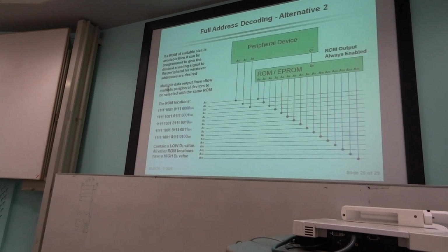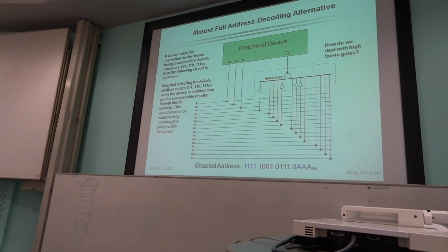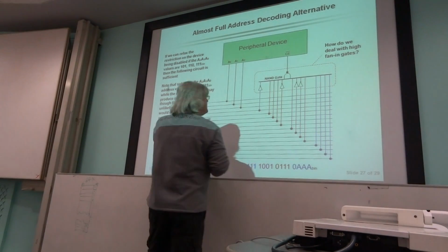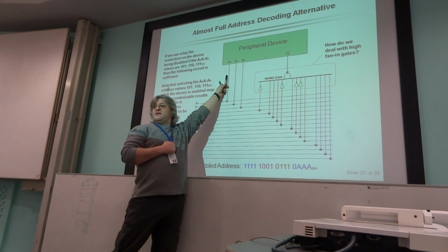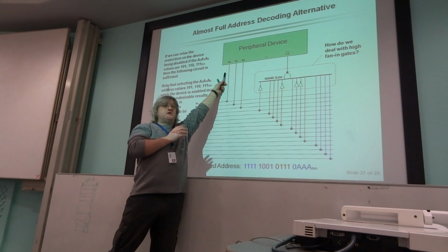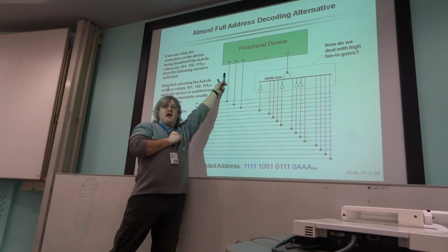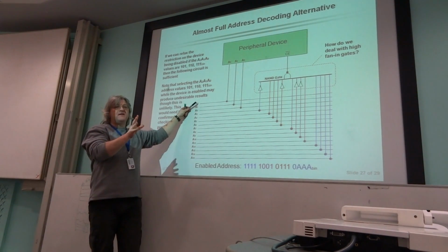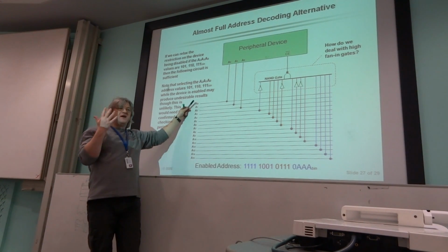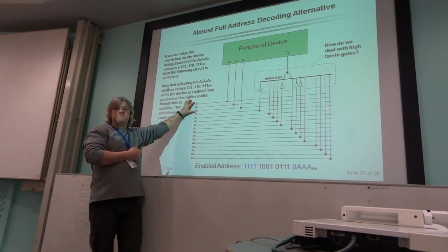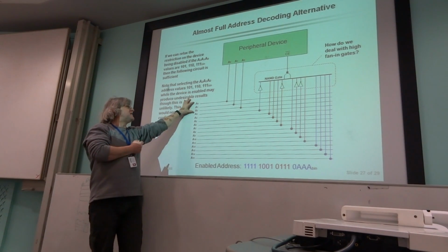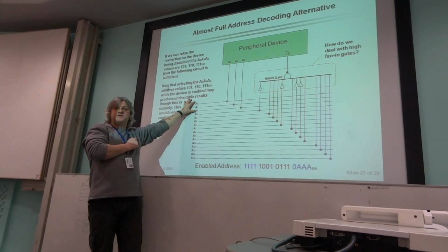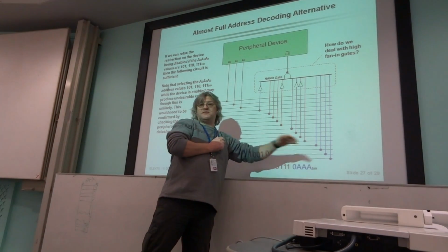So that's this last thing here. Now you'll notice that these 3 lines, A0, A1, A2, are being used to identify the different registers within this device, of which there are only 5. We're assuming it only has 5 internal locations. There are 8 combinations here, but we're going to assume now, for the other 3 combinations, it won't do anything damaging to this device. It's not going to matter, and nothing else connected to the address bus cares about those 3 values, provided this all holds true.